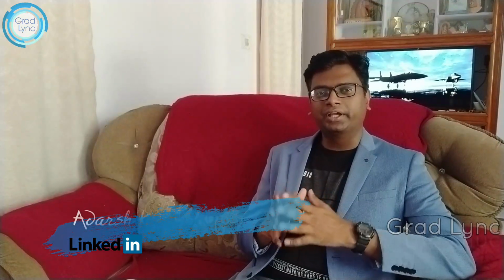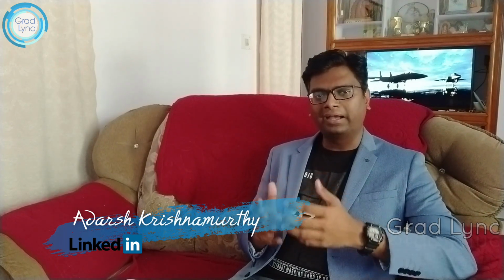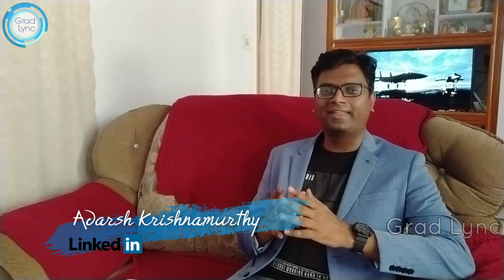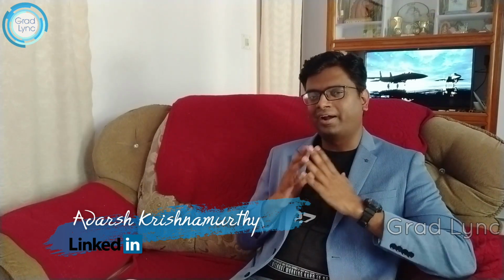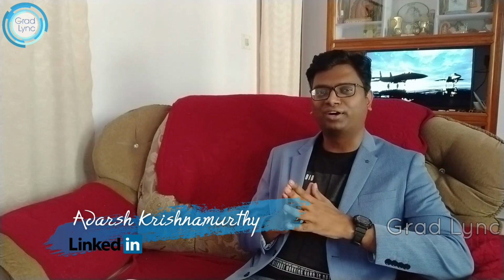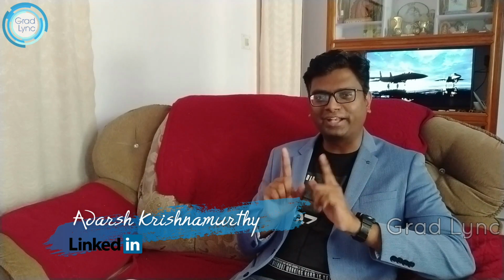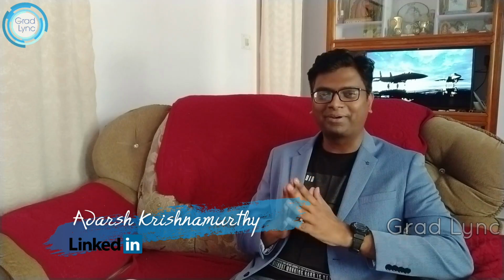I would like to introduce a new concept called critical Mach number. Mach number, all of us know, is the ratio of the velocity of an object to the velocity of sound in that medium. So that is Mach number. If I travel at a Mach number of 1, that means I am traveling at the speed of sound in that medium, right? When I say in that medium, that means with respect to the temperature in that medium. Why? Because the speed of sound depends on temperature.